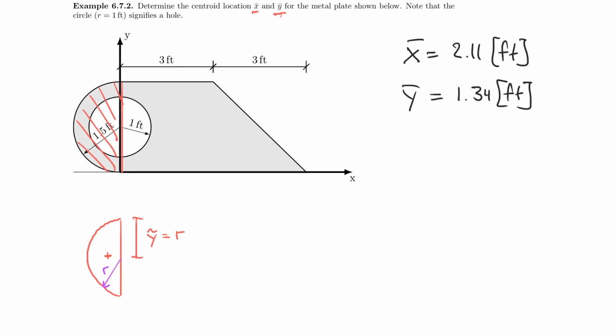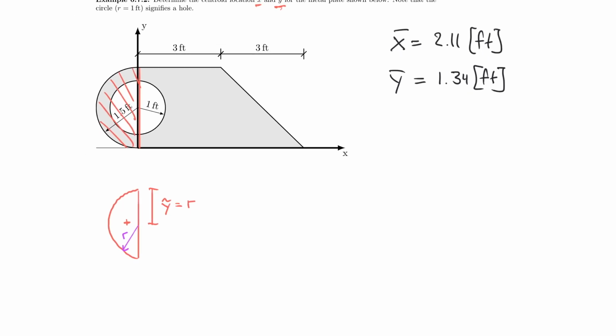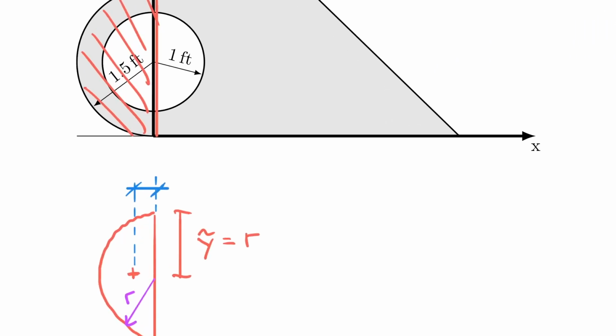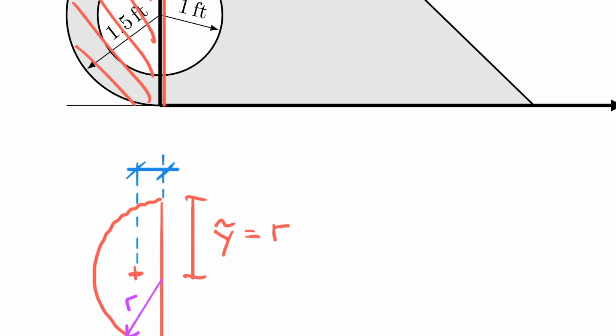But the distance that you probably have never seen before or never calculated before is actually this distance from here to here. And again, you can find this on the internet or in tabulated books or mechanics books and any mechanics reference. But for your convenience, I will tell you that this distance can be calculated by 4r divided by 3 pi.